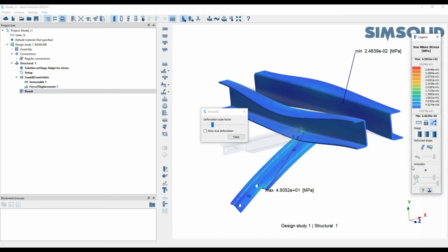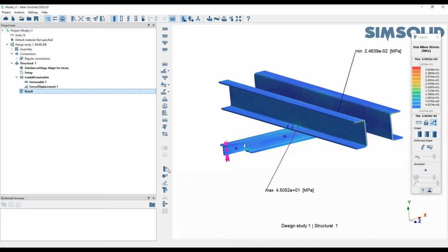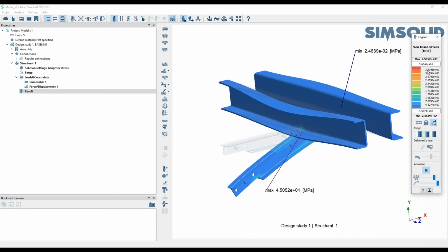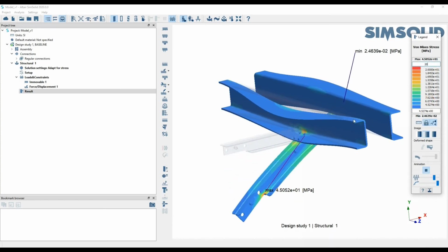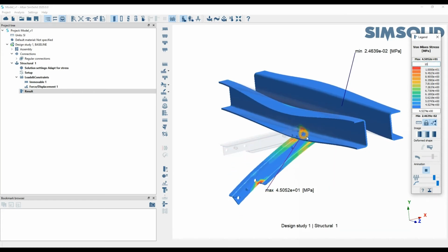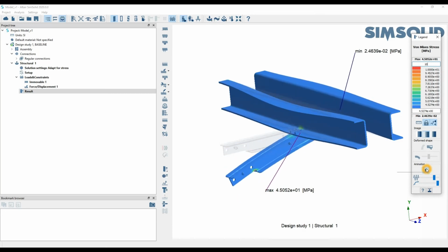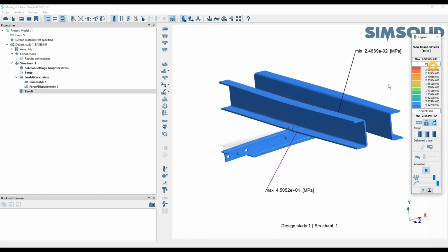Now by default you always get the same set of results. So you'll always get displacements, stresses and strains, and you can look at your stress contour plots in the form of a factor of safety as well. And obviously that's just done with respect to your material's yield value. You can also change your legend at the top, so your maximum values. If I specify 20, you can see there's a lot more areas which exceed the 20 mark, and if we do it to 10 as well, then you can see it done again. But I'll just leave that back at 30.